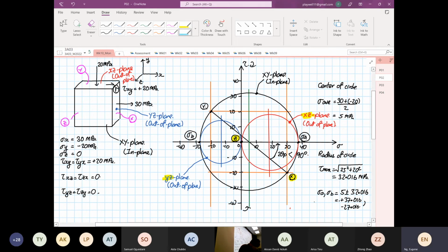Now let's look at the other circle. If we now focus on Y going to stress B, the angle is also equal to 2 theta P, and it's also less than 90 degrees. So the point going into the principal stress at less than 90 degrees is how you label the plane. Are we clear? It's not difficult at all. So this is the real life 3D Mohr circle.